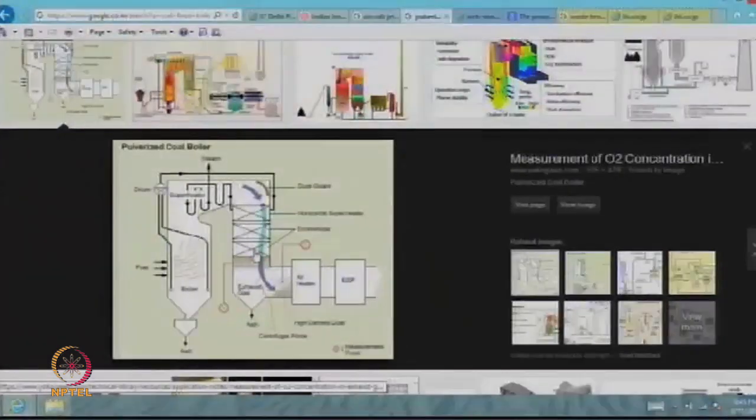As they go out, we put different types of surfaces in this, through which tubes in which water is flowing, or steam is flowing, or in one case even air is flowing. And everywhere you try to recover some of that heat and keep it in the system. So at the coldest end, what we have is the air heater, where we take ambient air, heat it up with the coldest gas, and then send it into the furnace for combustion. So we recover some more of that energy.